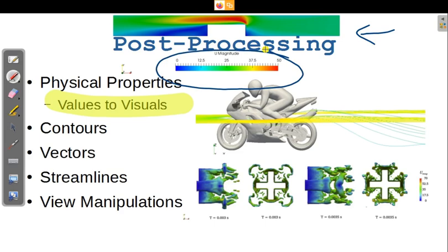And you see some blue color over the domain, on the rear part and the frontal part. So this is about the recirculation zone or the wake zone behind the domain. This is on this side. And on the frontal side, it is partially stagnating and partially recirculating. This is in a smaller aspect because those molecules are stagnant and subjected to some forces based on the motion of that particular box. So that's how this inference can be made.